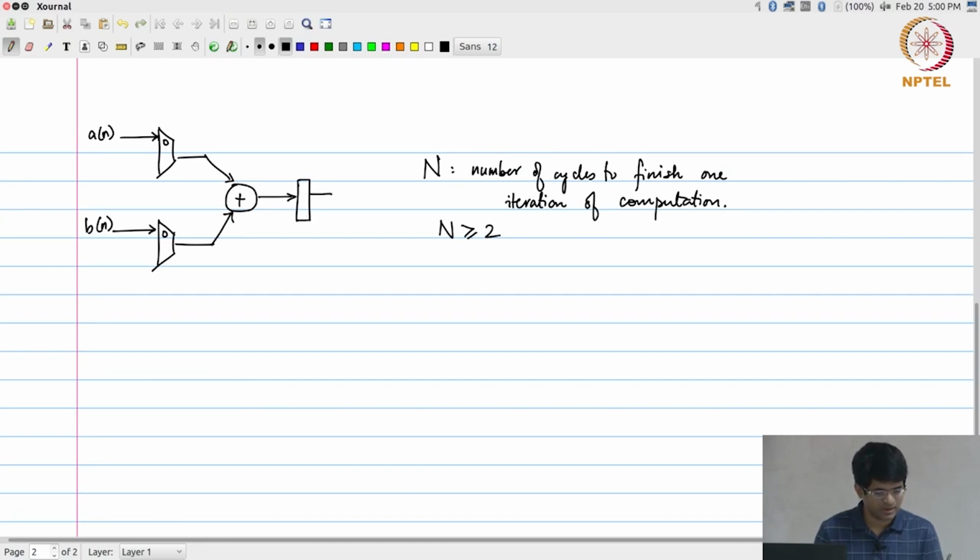So instead what I will do is I will just put a register out here. Take the output of this and say now what happens when the select signal of the multiplexers is equal to 1, right. I am going to feed C of n in there and the output of this register to the other multiplexer, right. Keep in mind that I could have switched it around. I could have fed the output of the register to the top multiplexer and C of n down here.